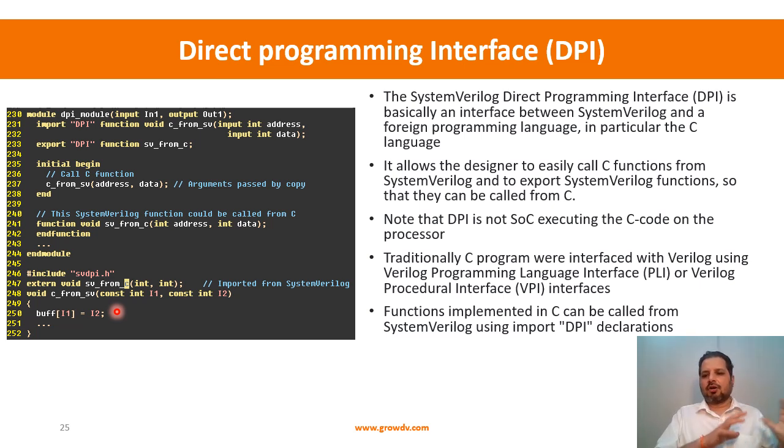ultimately our SystemVerilog and whatever we write gets converted into some sort of C object files, and then you link them. When you look at what it has littered in the work directories, you can find those traces actually. Based on that, I'm guessing. So because of that, I think interfacing C is sort of natural to this whole SystemVerilog.